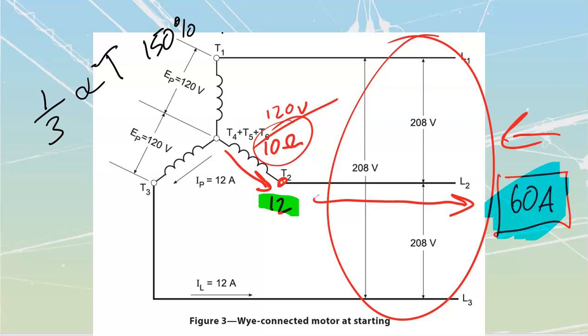And once again, we just have to reiterate that anytime we're doing any type of reduced voltage or reduced current startup, we always have to be aware that if I cannot start it under full across the line, I would not be able to start it like this. So you'd have to size it. This is 150% startup. You'd have to ask whether 1/3 of that, 50% startup, would be good to go to start this thing. You'd have to compare that with those torque charts, those curves that we saw, looking at those design classes.